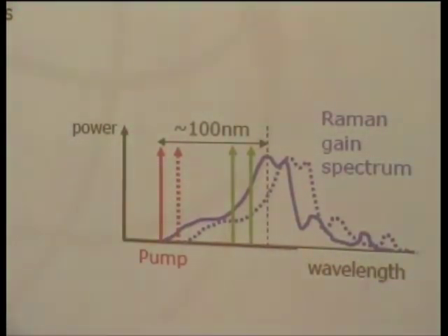As a result of such an effect, even if you transmit WDM signals at equal signal power levels, after such Raman scattering, the WDM signal will decrease in the short wavelength range and increase in the longer wavelength range. So there could be an imbalance between the WDM signals. As you saw in the previous section, you will need some gain equalization to compensate for such imbalance. So Raman scattering will also cause imbalance between the WDM signal channels, and this is problematic.